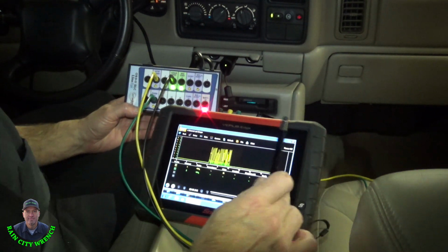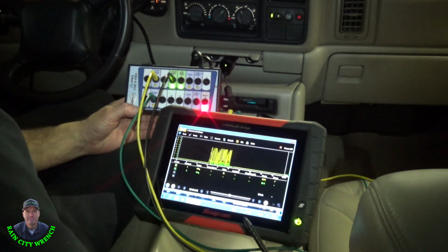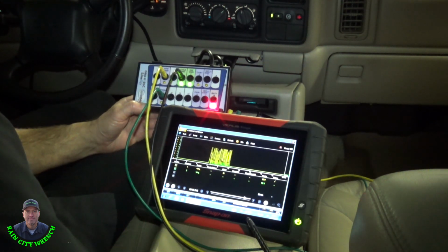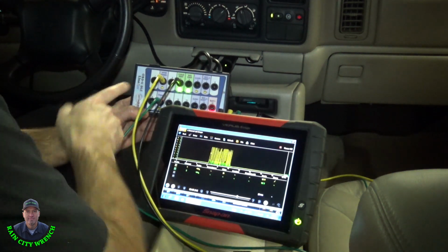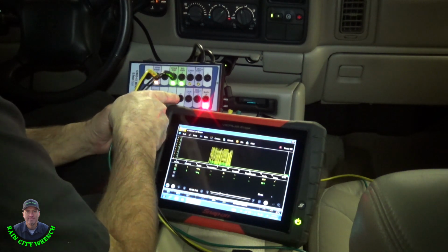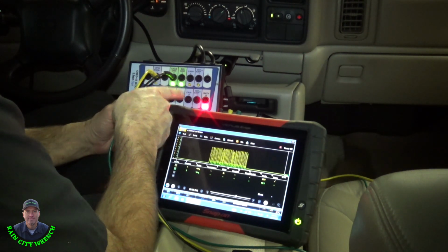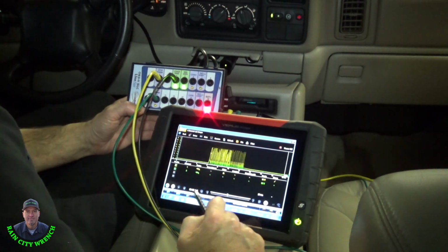I've actually never looked at this older vehicle on the network on a scope. And I think these are single wire. The CAN highs are dual, high and low, and they're a twisted pair. The wires are twisted and shielded.